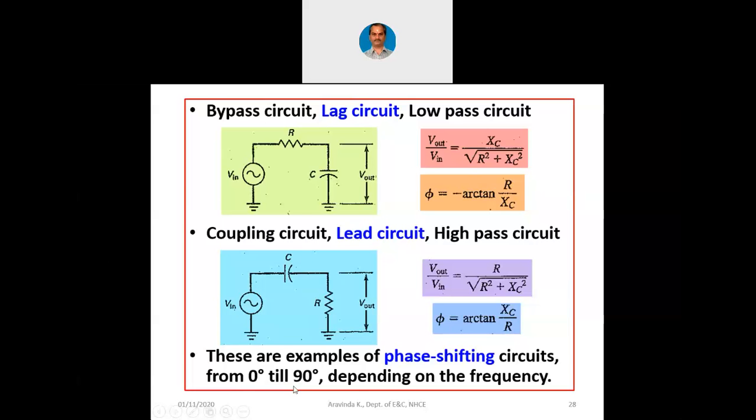So we do not use only 2 such circuits in the feedback network. The reason is the maximum angle itself is 90 degree. Now we can go between 0 to 90. That means either we can go for 3 or we can go for 4. We can go for still more circuits also. But here the point is, why should we unnecessarily connect more number of components in the feedback circuit? If the purpose is served by 3, we need not go for 4.